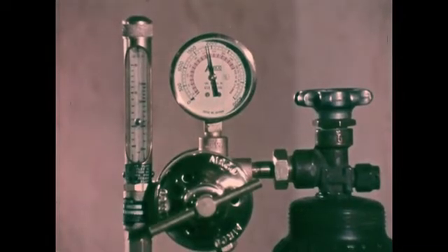The most widely used shielding gas for short-circuiting metal transfer welding is welding-grade carbon dioxide. This is particularly true for all mild steel applications. The gas flow for most short-circuiting applications is 15 to 18 cubic feet per hour. But in overhead work as shown here, or where drafts exist, the flow rate may be increased to ensure full protection of the molten weld metal.